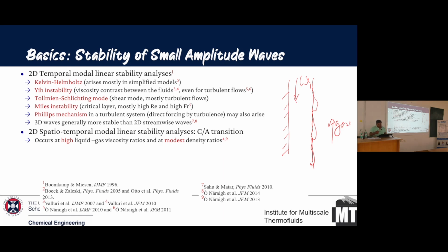If you keep increasing your gas flow rate, at some point, while the liquid is going down and the gas is flowing up, some of these waves actually become a standing wave. It's just a balance between surface tension, inertia and gravity. This point is called the loading condition.